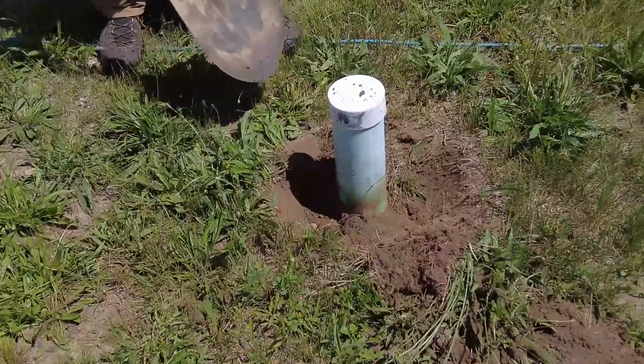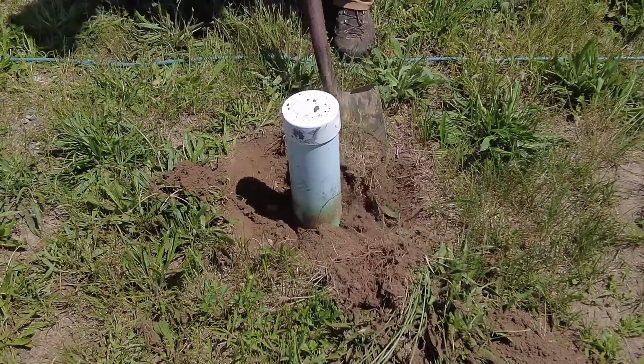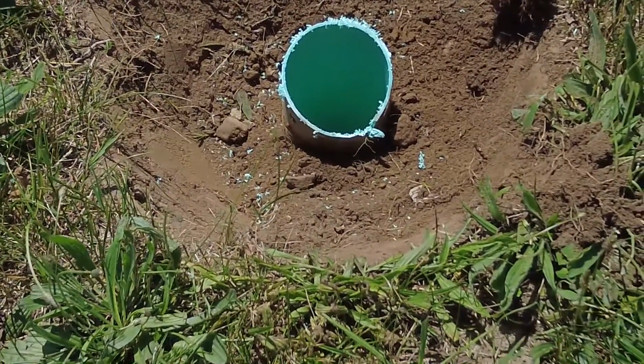And then they're going to come to a different conclusion about how that system is operating compared to if they got a good free-flowing sample. And in other instances, you have to dig it up each time. If you have to dig up a sampling port each time, you introduce a possibility of getting dirt and anything else while you're digging away into the sample itself. So it really begins right at the sampling port design phase and making it accessible.